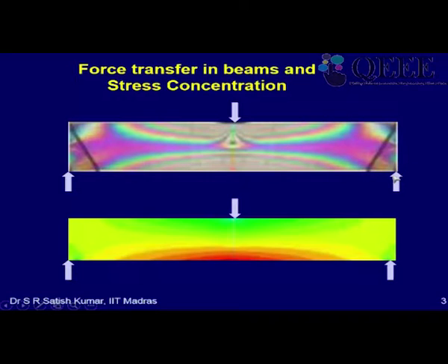So it is pretty complex, and we are just approximating this by our theory of pure bending or whatever, right? In fact, pure bending itself never occurs because most beams have UDL where shear is present throughout. And this is a screen capture of a finite element analysis of a beam subjected to a point load. Very coarse, so you don't see the stress concentration effects, but you can see a little bit here at the supports. So actually there will be a huge stress concentration at the point where we are applying the load.